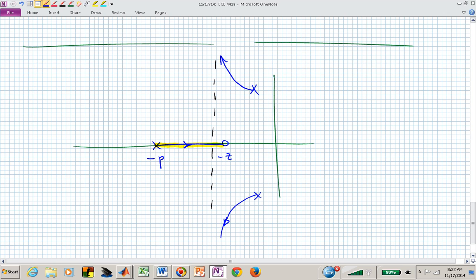How many poles am I going to have closed loop? How many closed loop poles will I have with this compensated system? I want to see fingers at the count of 3. 1, 2, 3. And I gave it away by saying I'm counting to 3. I should see 3 fingers. I have 3 open loop poles, and I have 3 closed loop poles.